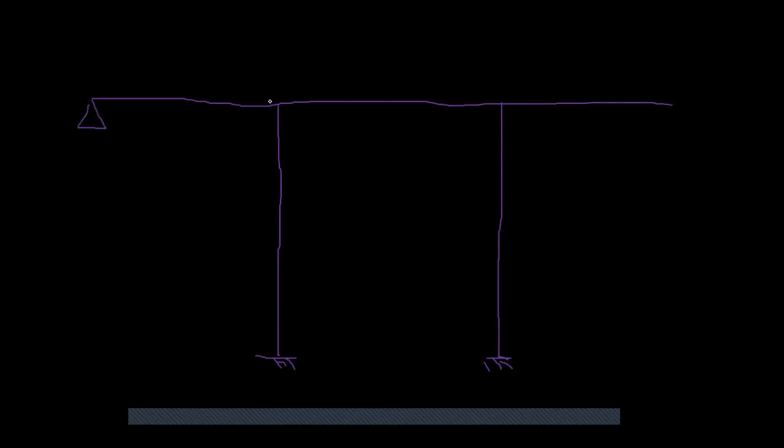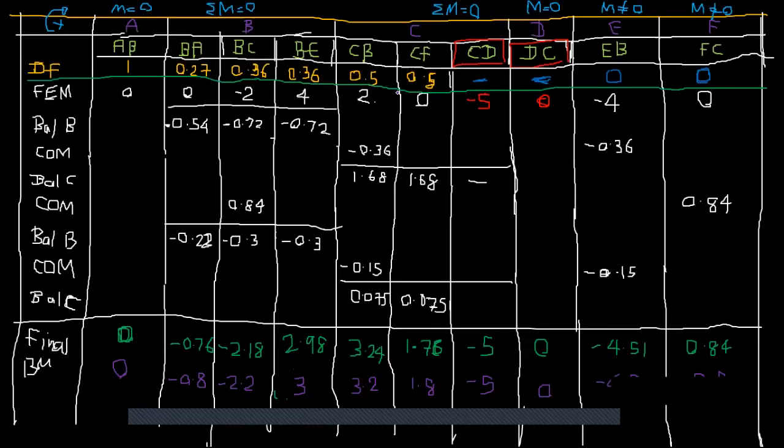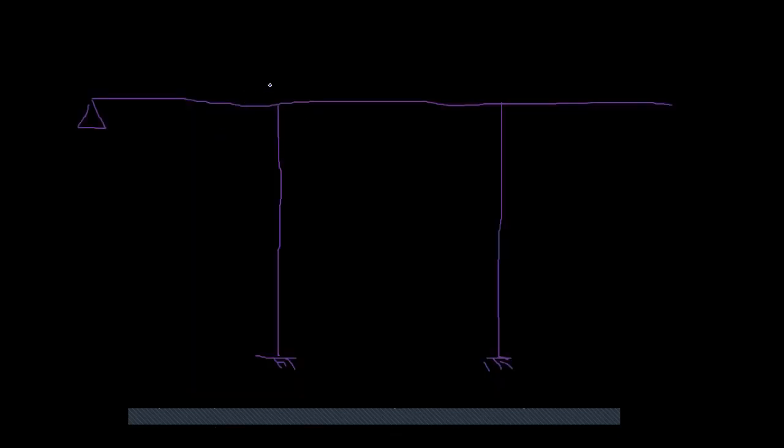Right. So I have the loading as well. So just draw the bending moment diagram. So it's here 0. At BA, it's anti-clockwise 0.8, right? So I showed you how to do this. If you consider BA, keep your finger here. For BA, it's anti-clockwise direction, right?